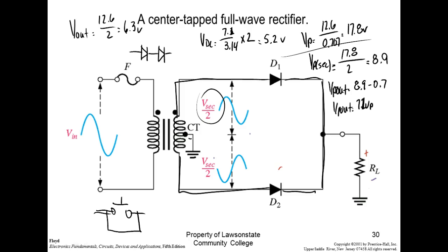Now the primary might be grounded. It's got the neutral. As soon as I go through that transformer, it isolates that. There is absolutely no neutral reference on the secondary side of the transformer. So that's why they got that ground rod on your house. Because if they didn't do that, then what? When it goes to that transformer, it would lose that ground. Well, that's not true. They grounded it twice. They grounded at the transformer and they grounded at your house.